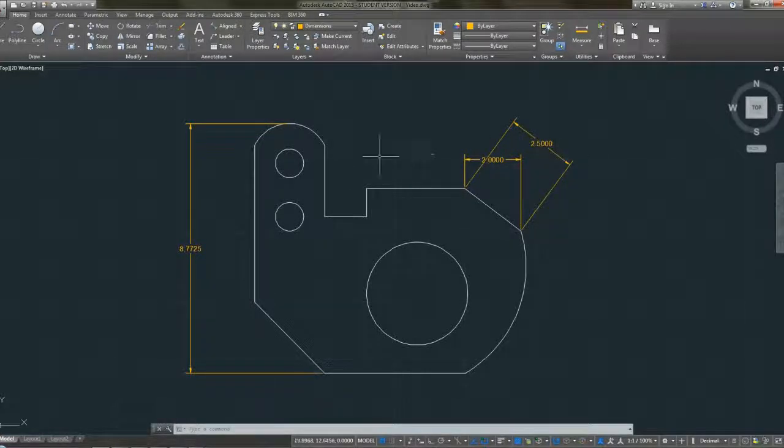I will now use the angular dimension, which is over here. We click angular. To create one, we need to select one line, which is this, and then another line, and then pull it up. There's a difference between this dimension and the other one though. So you can see we have 135 degrees here, and then we can move it over here. We have 45 degrees. Move it under 135 degrees, 45 degrees, but we're going to leave it right here for now.